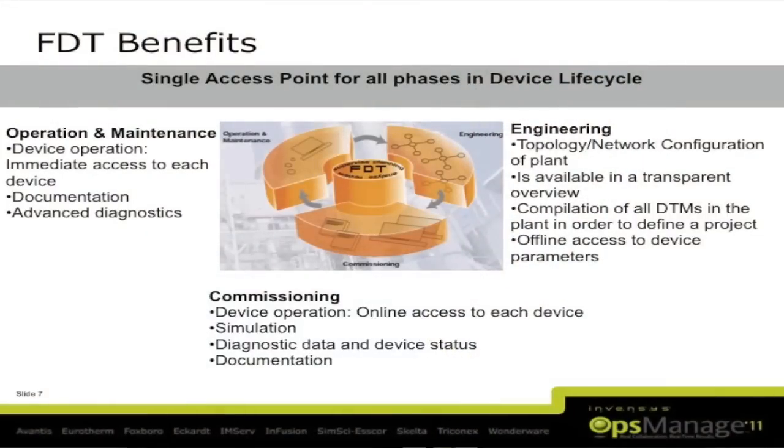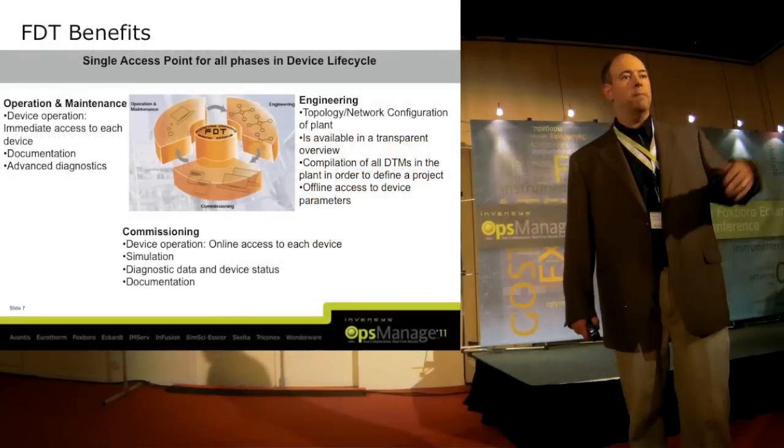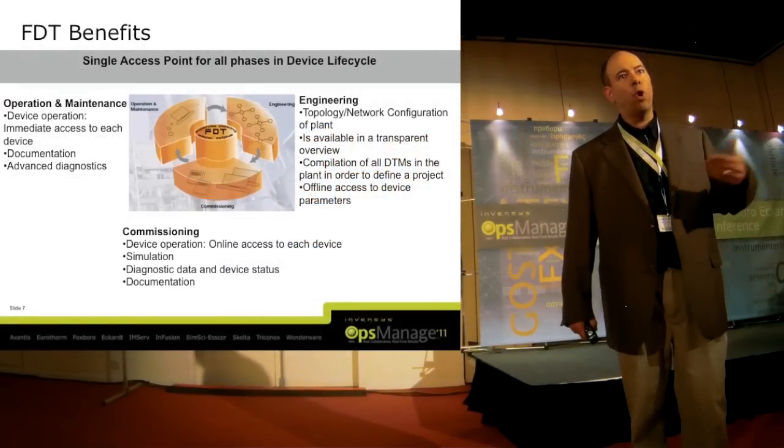So the benefits of a DTM. Device operation, immediate access to each device, easier commissioning, easier user experience, a concise and coordinated location for all your DTMs beyond one vendor. So a frame application can not only host our DTM, it could host some other transmitter that we don't offer as DTM.